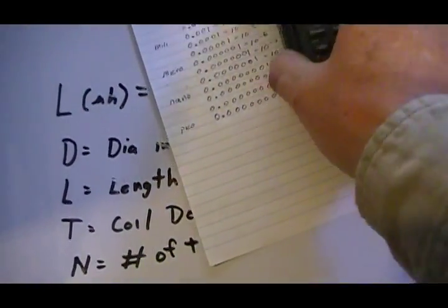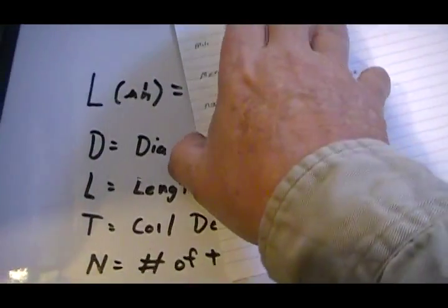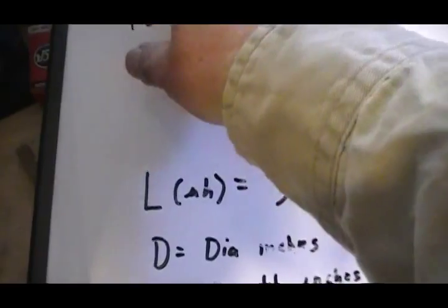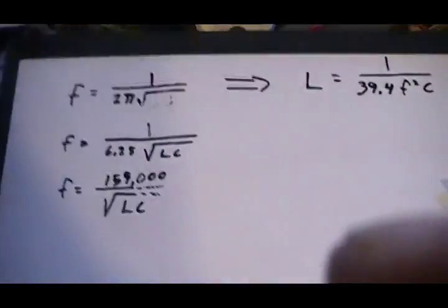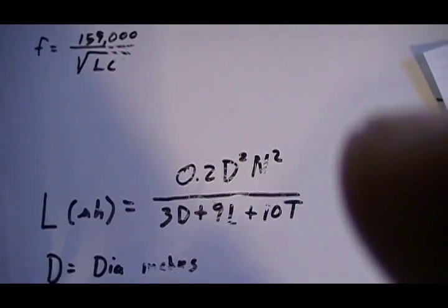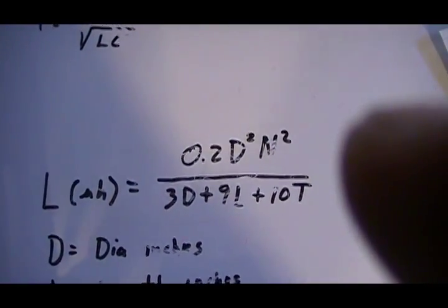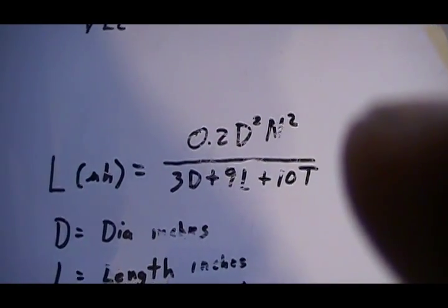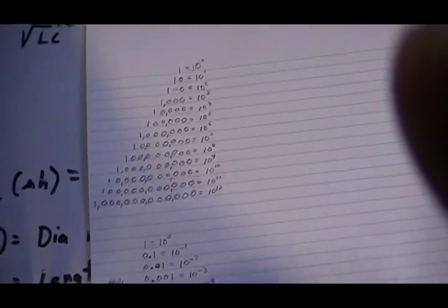It makes it a lot easier if you need to do this math, which I'm really messing up, but that way you can leave the formula in the base formula. You can punch in L and C as micro or nano henries, and capacitance in picofarads and stuff like that. You can use the scientific notation, punch it into the calculator, and get an answer of real-time frequency of what the frequency will be.